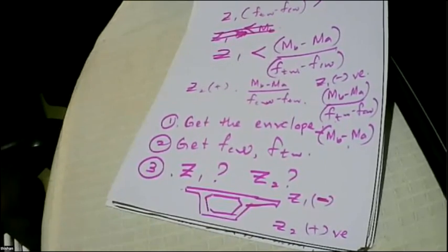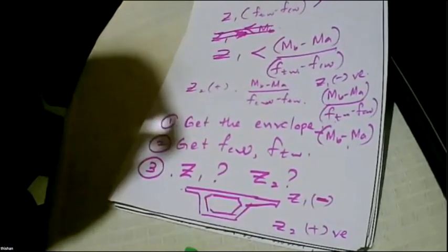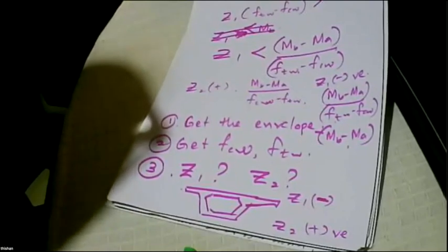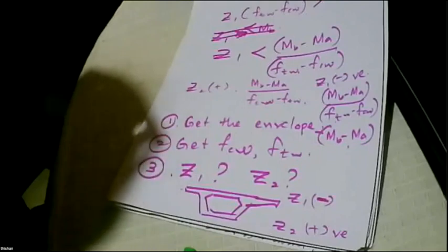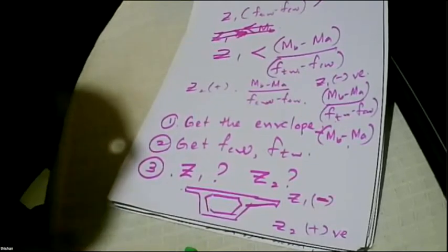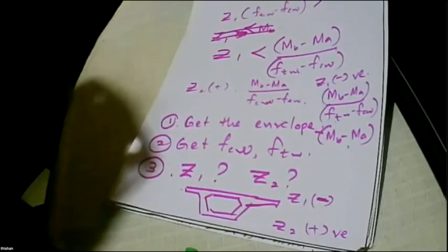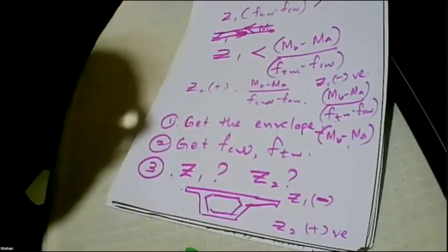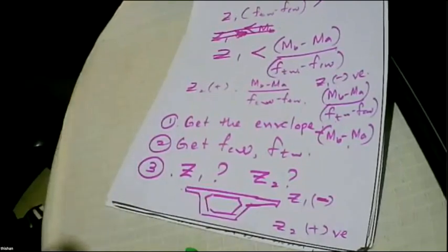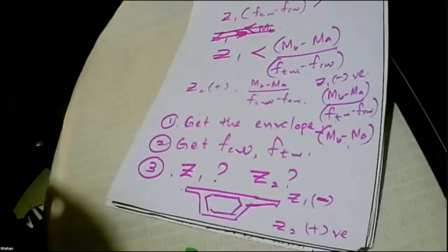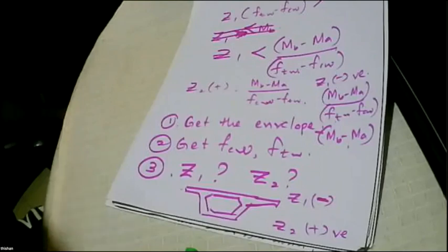Yes, sir. Can you remember, I gave a chart to find the section for Y beams. So even if a person is not a bridge engineer, straight away he can say what is the bridge that will work for a given span, right? But we don't have any chart like that for box girders. So what are we going to do? We will not worry about the section. We'll develop a bending moment diagram under elastic conditions. From the bending moment diagrams, we can get the envelope. From the envelope, we can get the range. And once you know the range, straight away we know what is the minimum size needed. So we select a section which is larger than that. Is that clear? Yes, sir.